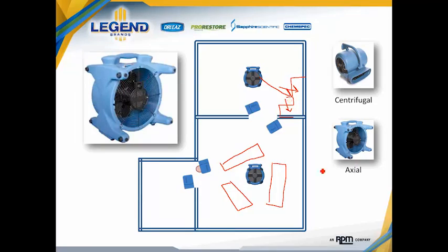So that's the general strategy on air movement. Notice here, by the way, as just a general principle for installation, that all of the air movement in every one of these rooms was in a clockwise orientation. If you're using this particular air mover, that clockwise orientation is critical because, again, the intake for the air mover is on this left-hand side only. That, on this analogy, would be on this side of the air mover. This side of the air mover is not an intake.